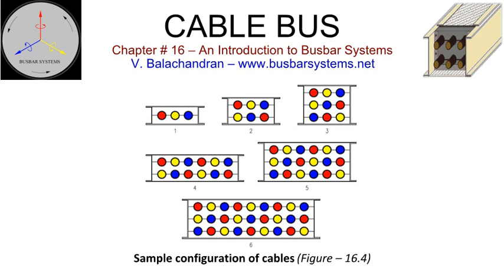Cable ranging from a diameter of 3 mm, 1/8 inch, to 99 mm, 4 inches, may be covered by 7 sizes of plugs. Fire stops may be provided, if specified. The fire stop for a cable bus differs from that installed in a bus duct since the cable is already insulated for the rated basic insulation level.